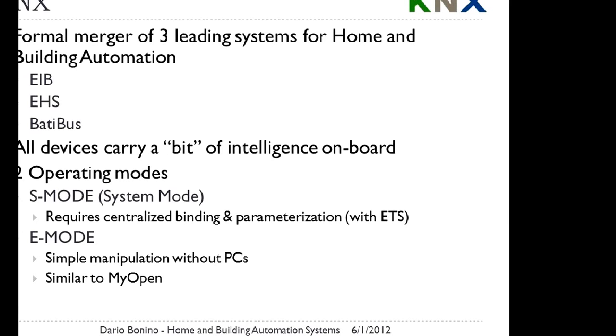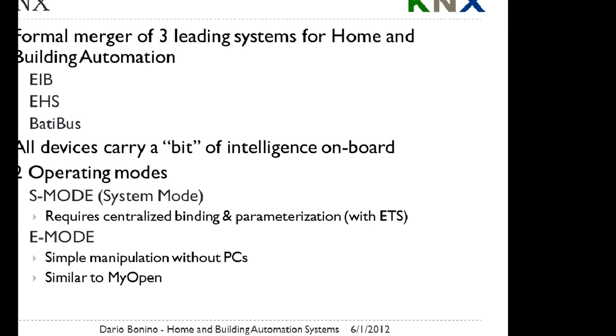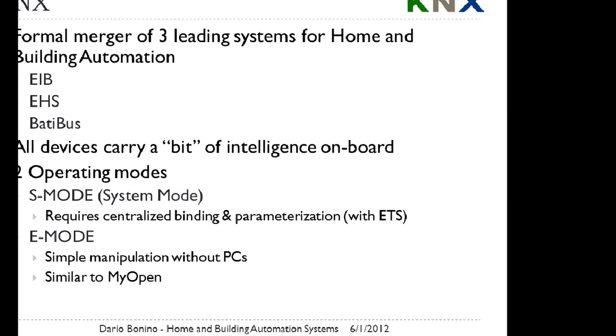And it's complex. Even more complex than programming using ETS, especially if you are used to using ETS. So almost all KNX installers are using ETS, and they almost completely ignore the E mode. And this is reflected by the fact that the devices supporting the E mode are much fewer than the ones supporting S mode.